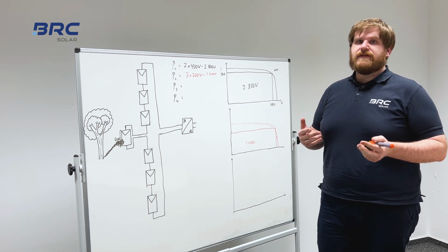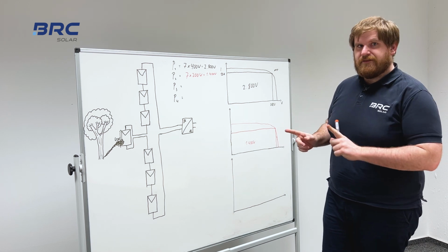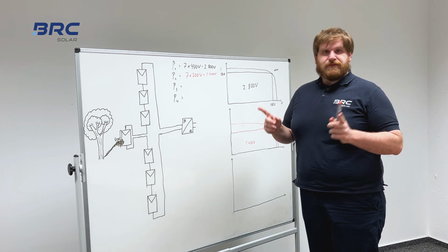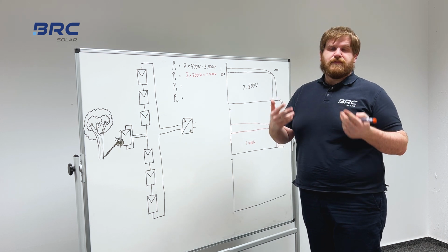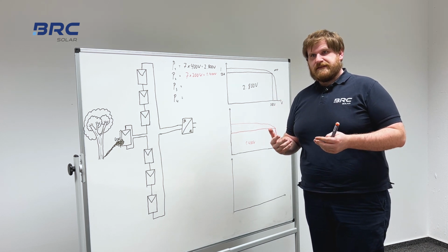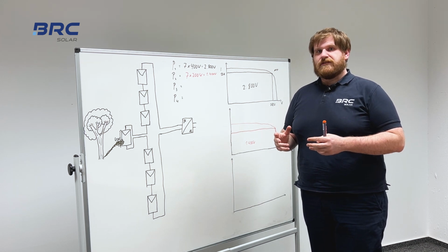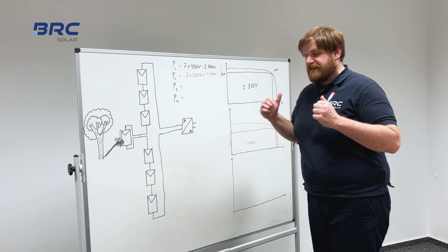New inverters have so-called global MPP tracking, and they act differently. If they detect that one or more modules can't produce the current they want, they would activate the bypass diodes. In each module today we have bypass diodes installed in the junction box of the modules in the back.